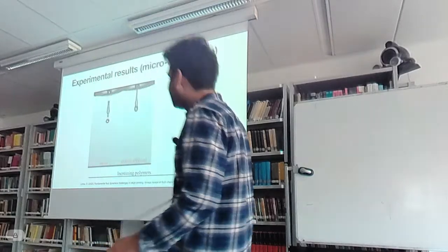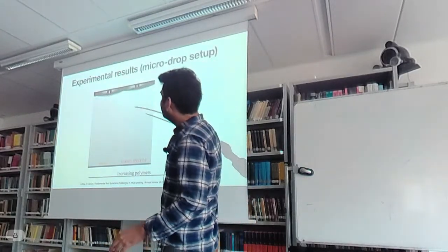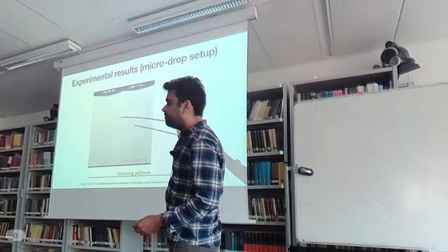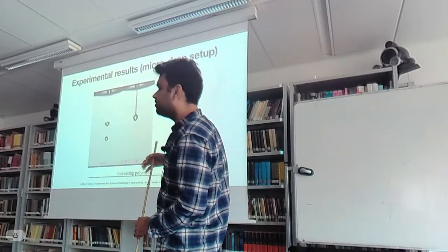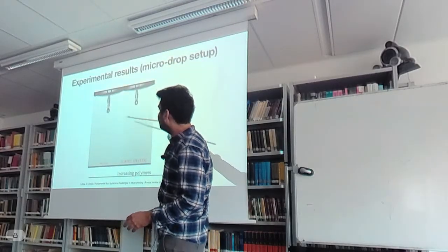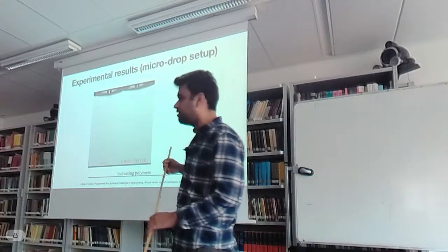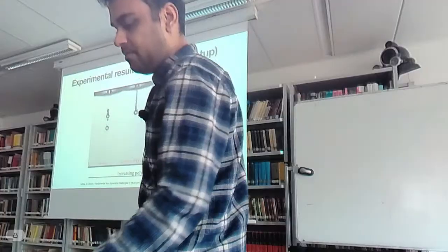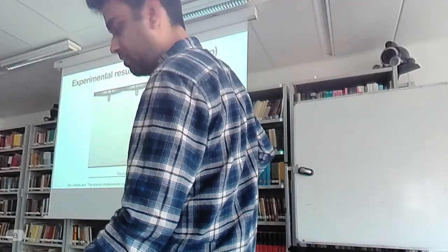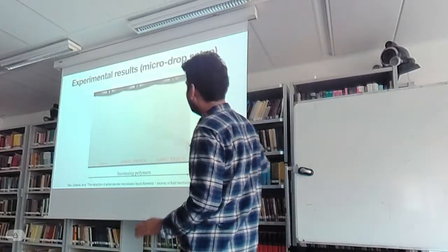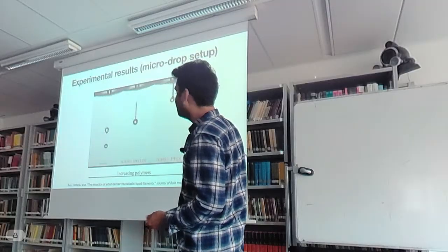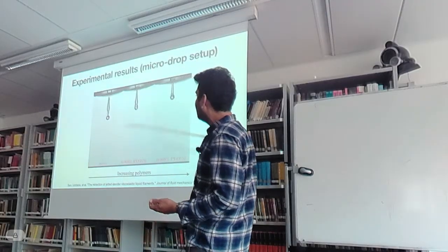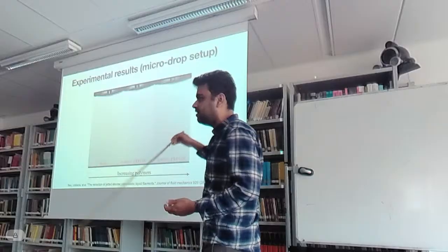The moment you add some amount of polymer, you see that this tail droplet remains attached to the head droplet. So you suppress the second breakup that happens there. Also this jet is a bit slower than the first one. If you add a bit more polymer, you can reach a situation where you don't have breakup altogether and this jet retracts back into the nozzle.